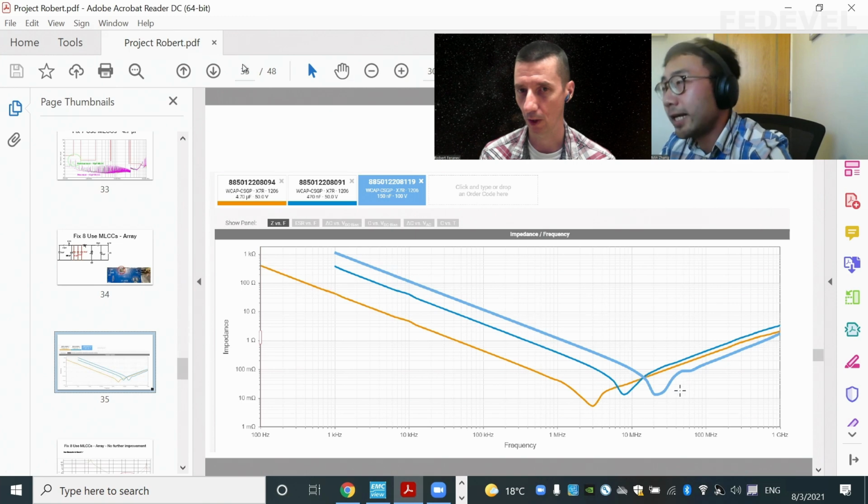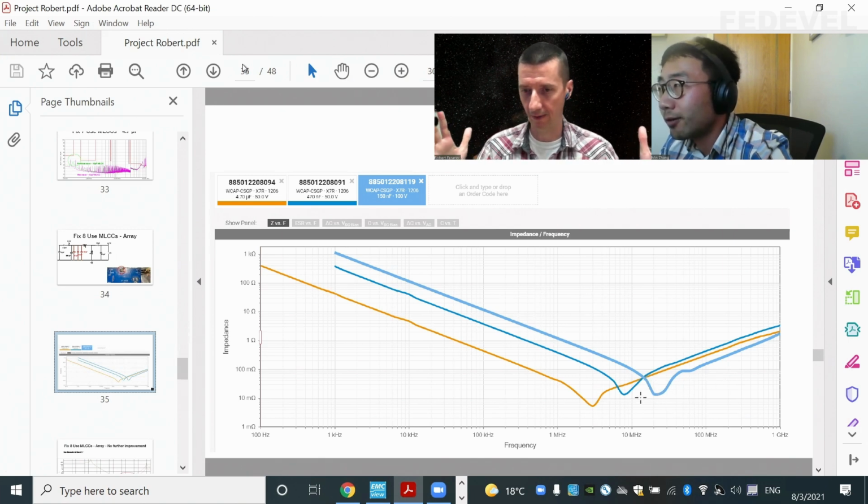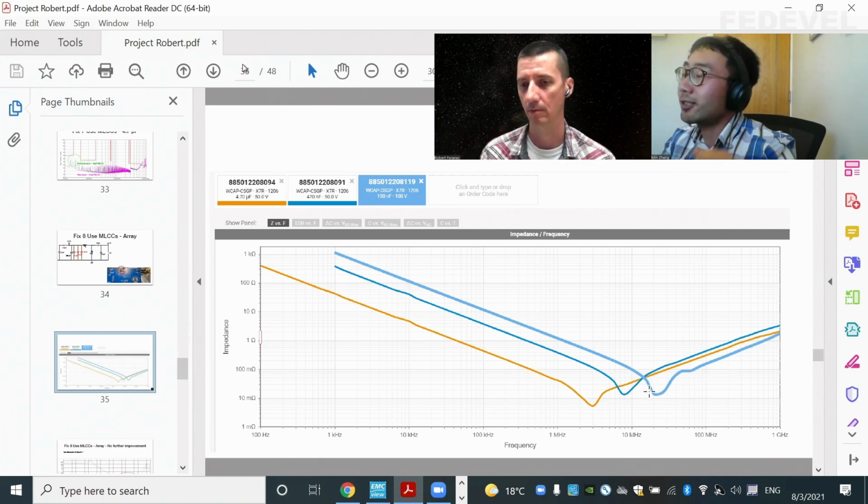That's low impedance. The low impedance is often the impedance value close to the self-resonant points of ceramic capacitance. So what you want to do is select 3 or 4 or 5 capacitors, with resonance points that cover each frequency range. So overall, you achieve a wider frequency range like this. In wider frequency range, yes.